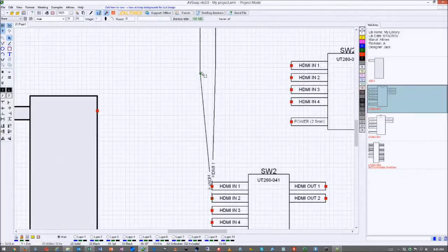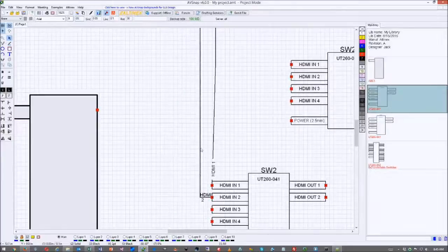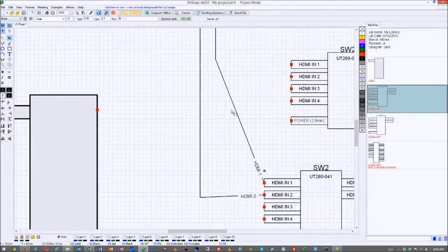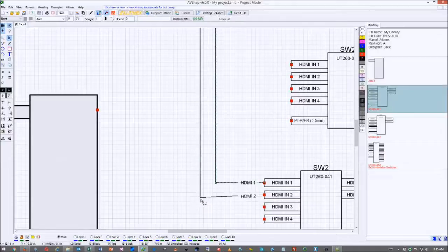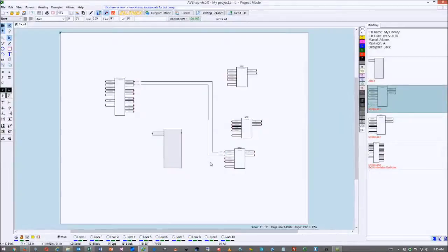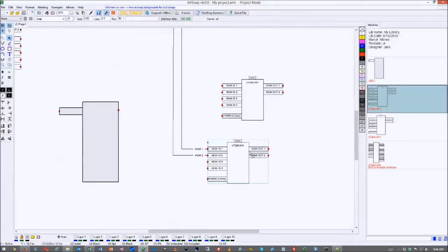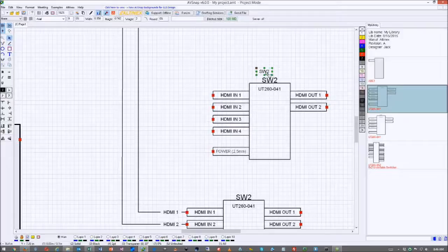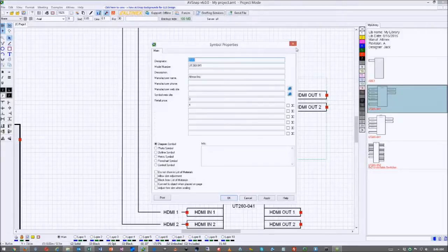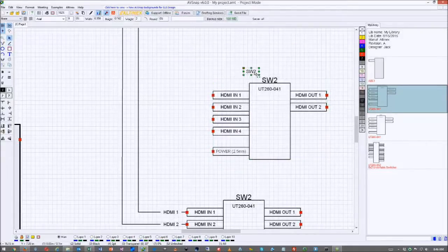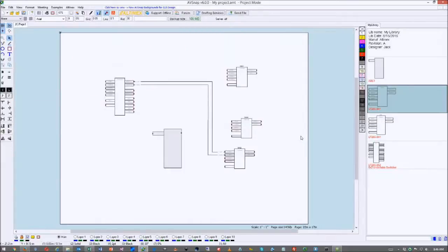No problem. Yeah, sometimes we add things and I forget why we add them. You don't use it that often. But I remember there was a function where you select the symbol and press letter J, and you see it also puts SW. So for every symbol, if you press letter J, it gives you the designator right away. But in this case, it's permanent. So whenever you move it in, you just see that designator as part of the symbol. Yeah, that's awesome. Thanks. Frankie actually was the one that told me that's what it was for.